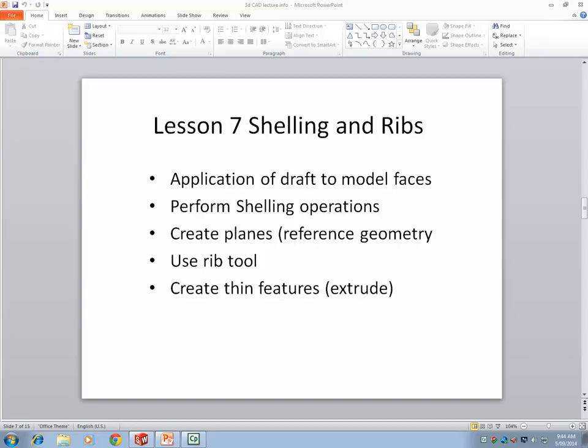Quite an important tool. Convert entities will help you to not draw your sketches from scratch. Existing part, existing model, if anything is useful of the edges, offsets, mirrors, you can always use convert entities.